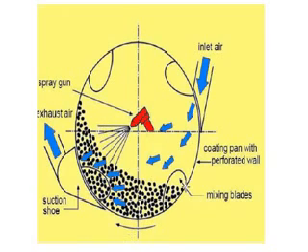See, this is the one diagram I have shown here. Here these are your tablets, or it is called the bed, and here this is your gun which has the ability to spray your coating solution on the surface of the tablet. Along with this, we have to provide inlet air for the very quick drying of your tablet, or complete removal of the solvent.